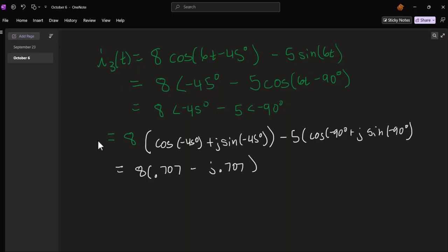Admittance, you're not going to use that much, but in the future you'll have some professors that like conductance instead of reactance, and there'll be some that like admittance instead of impedance. So Y is just 1 over Z. So it's just the inverse. And admittance, just like impedance has units ohms, just like reactance, admittance has units Siemens.